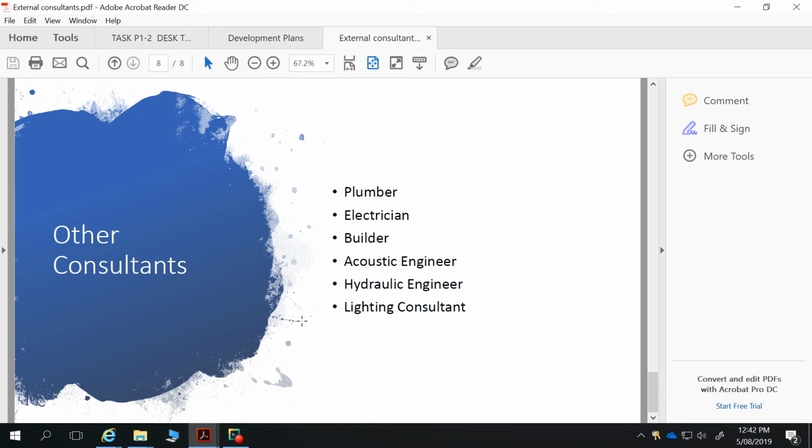these are the acceptable levels of voltage drop. So SA Power Networks say that we supply power at this particular voltage within these parameters. These are the allowable parameters of voltage drop that we can have. So you want that electrician to say, we need a cable this fat to run that distance. It's going to cost you $70,000 to do that. And you go, we're going to go with an autonomous power supply for building that area, or choose a different spot. So not always, but sometimes you want an electrician.